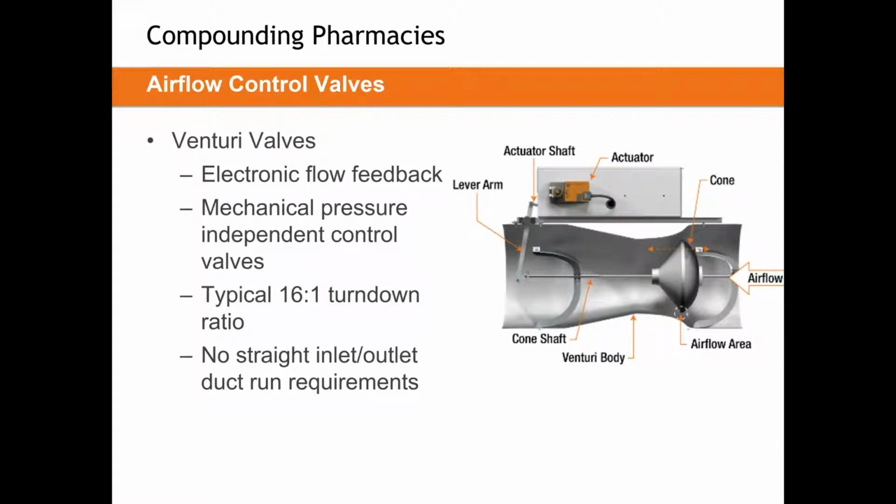That's compounded with what's actually inside that cone. There's a highly engineered spring inside that cone. So as the pressure drop changes in a system, this cone and spring assembly will shift forward and backwards. Basically, at higher pressure, it will compress farther into the valve. At lower pressures, it will expand out of the valve.